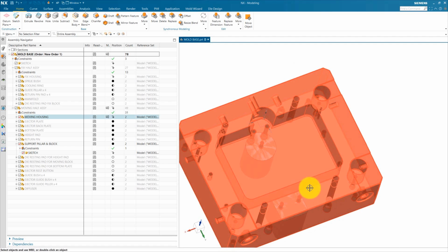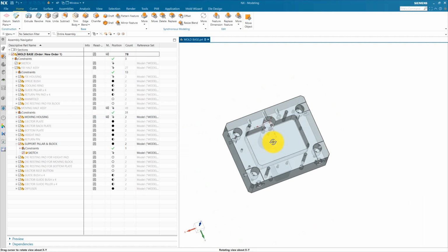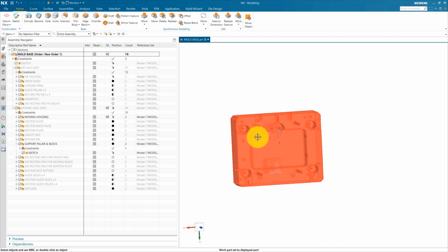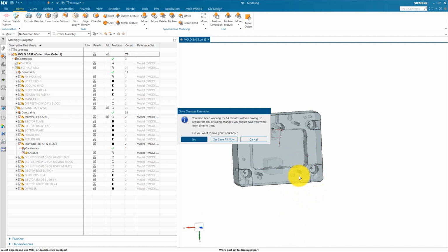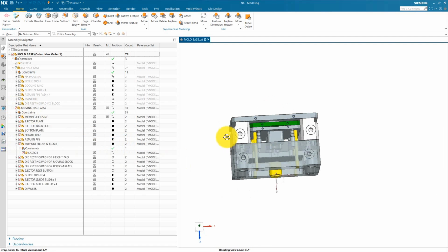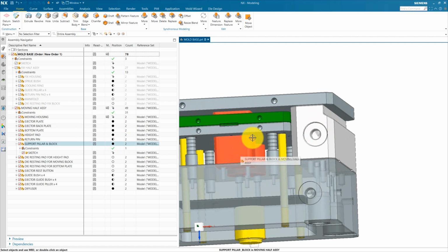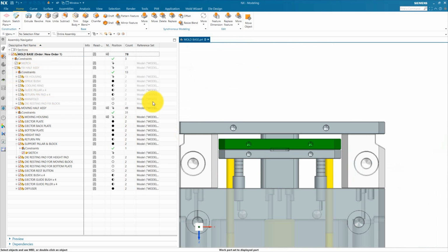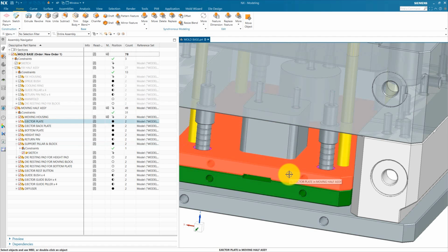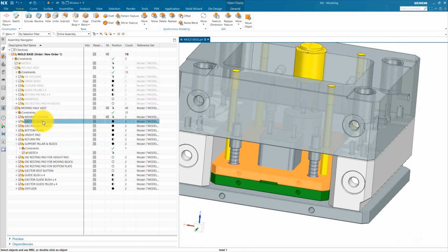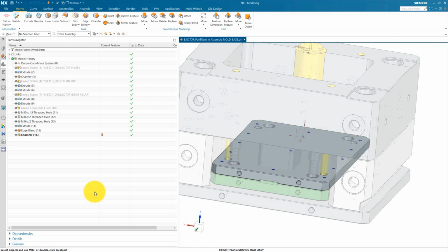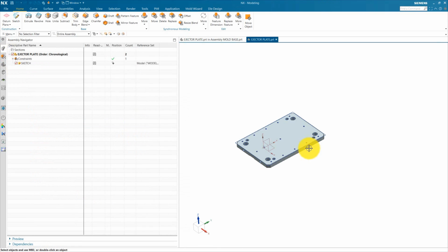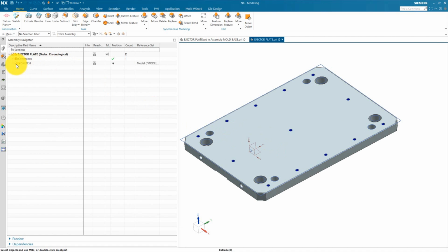So make sure one support block or pillar is provided backside of the diffuser and one in the bottom side. Okay, minimum. You can also add more support pillar and block if there is a place. Now our moving housing assembly, our support pillar is added and exactly touches the bottom plate. Next, we need to add that inside our ejector and ejector back plate. Activate our ejector plate. Go to ejector plate part navigator. We are going to open this ejector plate in individual window so we can see easily.